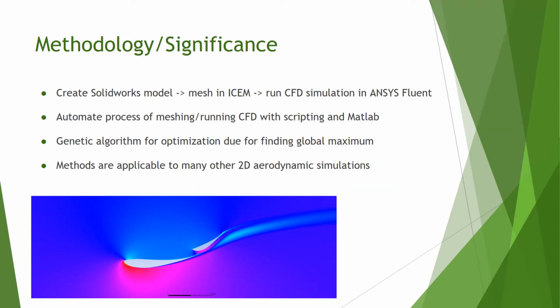The methodology involves a geometry that has been made in SOLIDWORKS, imported into ICEM, which is a meshing software. The mesh is created to be fine enough to calculate the boundary layer forces on the airfoil, and the whole model is imported to ANSYS Fluent. The CFD solver runs inside ANSYS Fluent itself. The whole process can be automated via scripting in MATLAB.